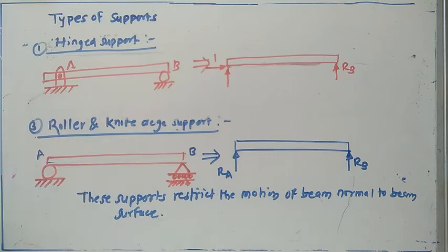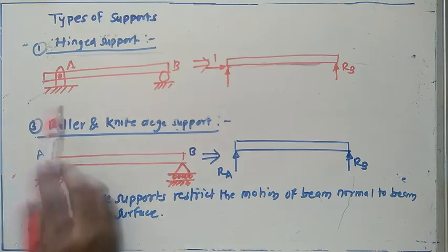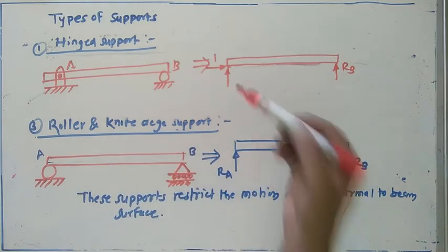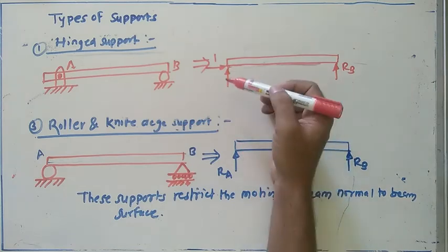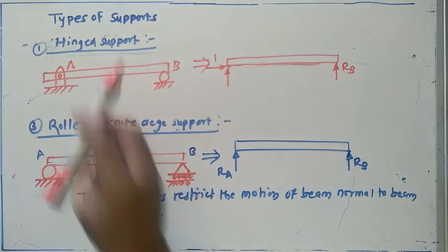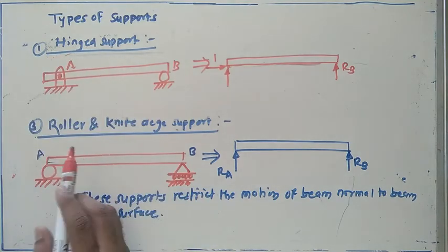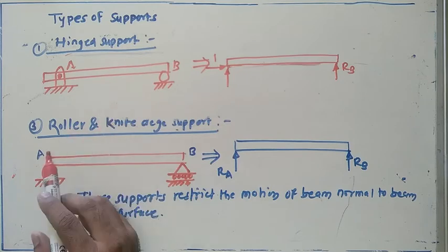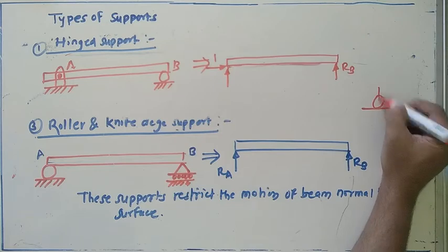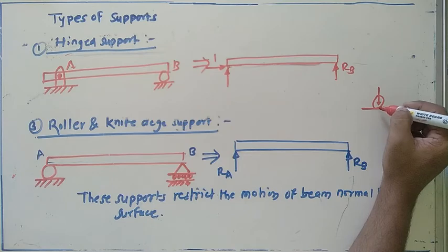Now one more important thing related to all the types of support: the reaction comes where the motion is locked. That point is very important. In the previous case, we discussed first the frictionless support. In case of the frictionless support, the motion of this particular roller is restricted in the vertically upward and downward directions because the obstacle is here.